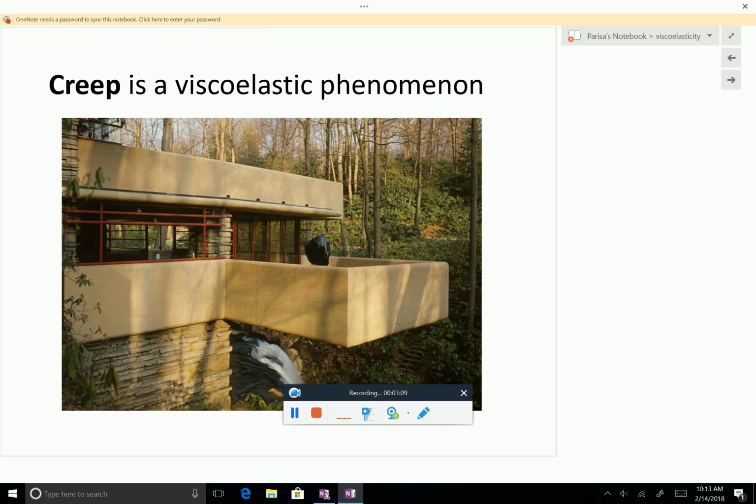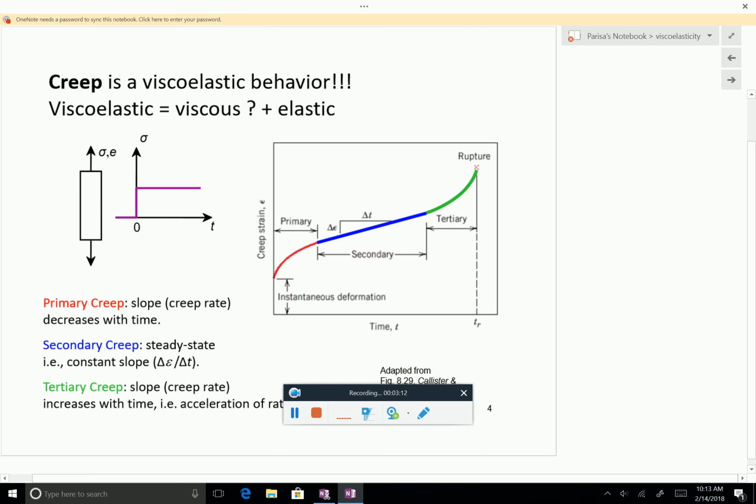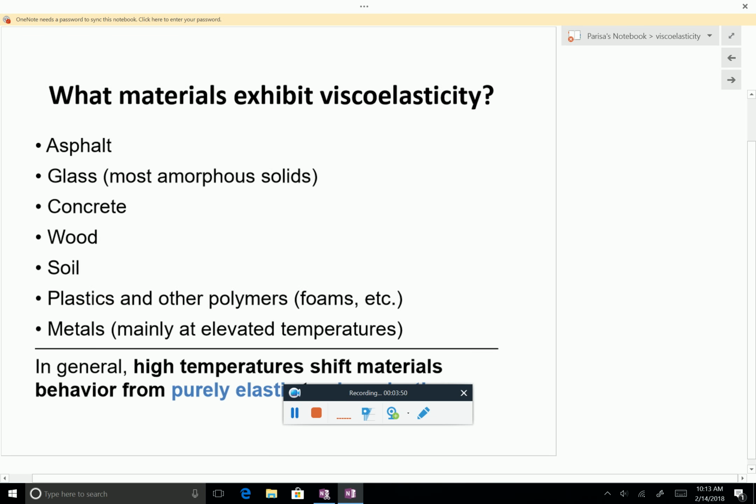And it's a big problem, as you remember here. It's a good example, but in general, the amount of creep strain can be very, very large. So you can have this much elastic strain, but then because of creep versus time, the strain keeps increasing. First very fast, then it kind of becomes steady, and then towards the end, it can be very fast, and then the material breaks. The models that we have so far seen, none of them describes this kind of behavior. So we need to learn a little bit more. We need to have better models.